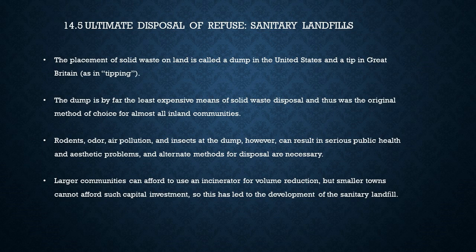The dump is by far the least expensive means of solid waste disposal and thus was the original method of choice for almost all inland communities. Rodents, odor, air pollution, and insects at the dump, however, can result in serious public health and aesthetic problems, and alternate methods for disposal are necessary. Larger communities can afford to use an incinerator for volume reduction, but smaller towns cannot afford such capital investment, so this has led to the development of the sanitary landfill.